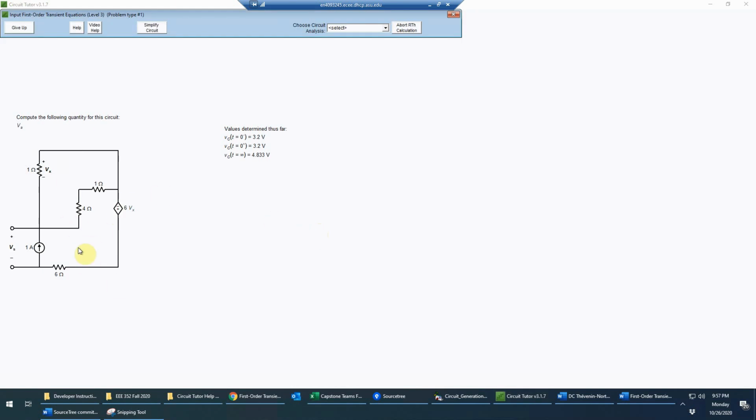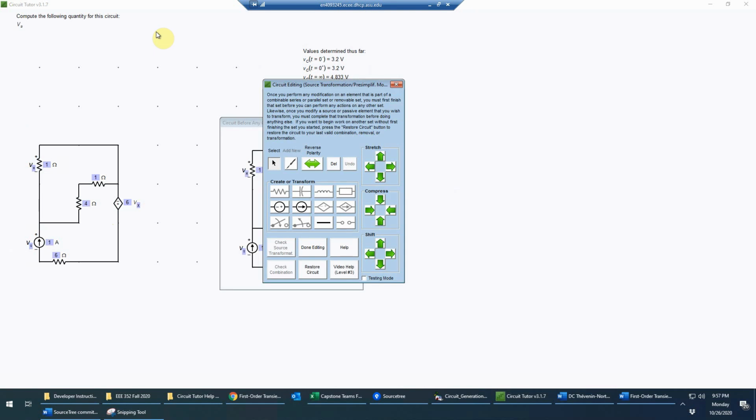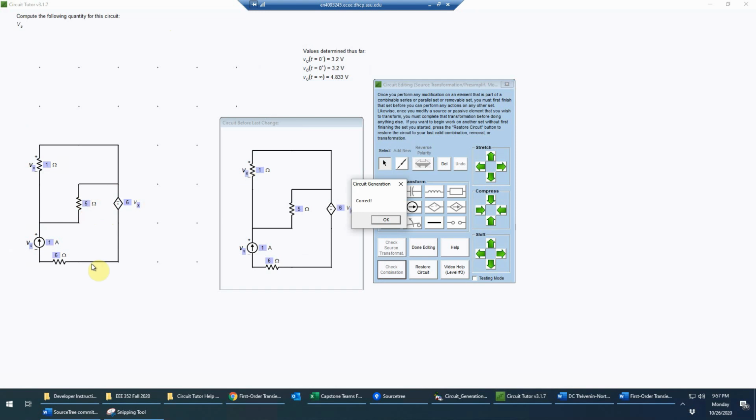We can, however, go back into simplification mode to simplify a little bit, perhaps. So we do have 2 resistors in series there, so we might as well just combine those and make that a 5 ohm instead of the 4 + 1 ohms. So since those are in series, we'll just combine them like that. And having done that, in fact, we notice that we now have actually 2 resistors in parallel, namely the 1 ohm and the 5 ohm.